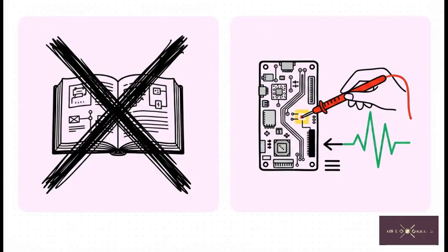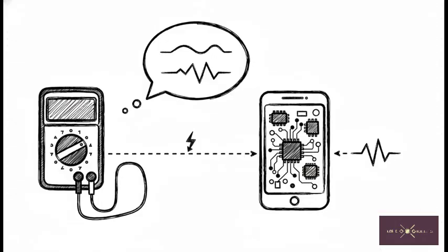We're using the buzzer mode on our multimeter to test the precise relationship between a specific path or a line on the board and the ground. We're not hunting for a highly precise digital resistance number to write down. Instead, we're quickly testing the overall health status of a path relative to the ground. So, how does this actually work under the hood? Well, when you set your multimeter to buzzer mode and touch those probes to the board, your multimeter's internal battery pushes a tiny safe voltage right through the path you're testing. The multimeter then measures the current that manages to return back to it.